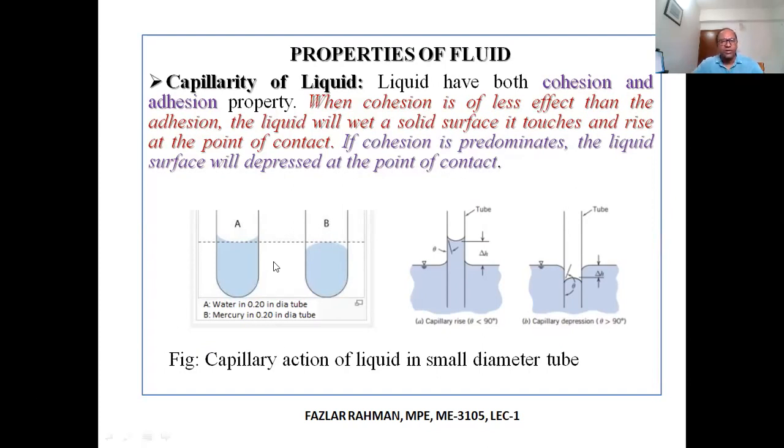How? Because you see this small triangular portion of the fluid, it has a certain weight, right? If I simplify the view close to the wall, we have a fluid, right? So how is this fluid staying over here? Along this surface, the fluid will experience tension, surface tension along this direction, right? Because it has both properties, cohesive and adhesive, but adhesive property is dominant.